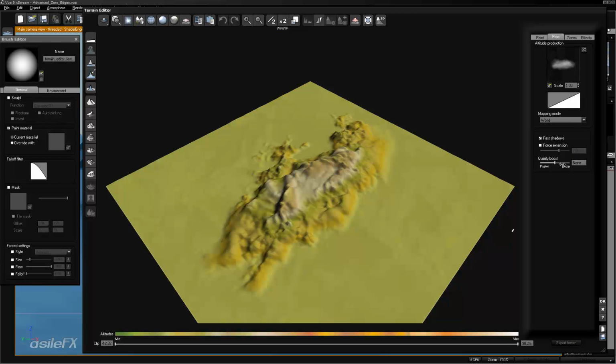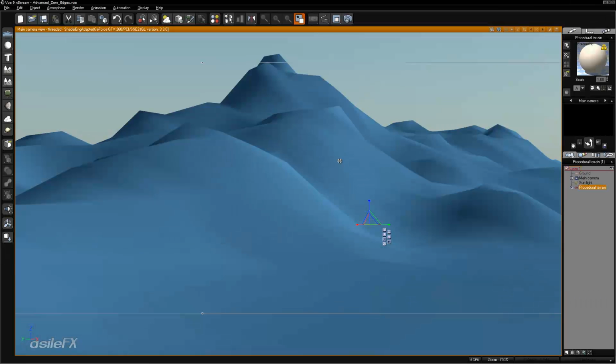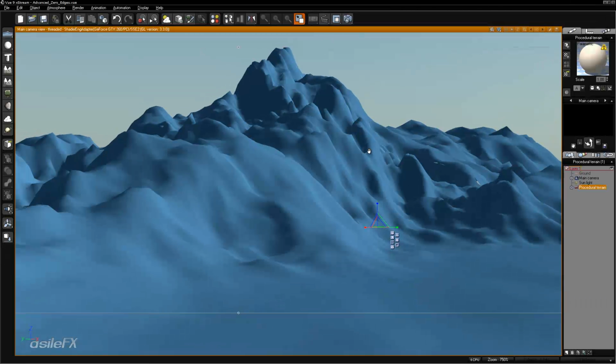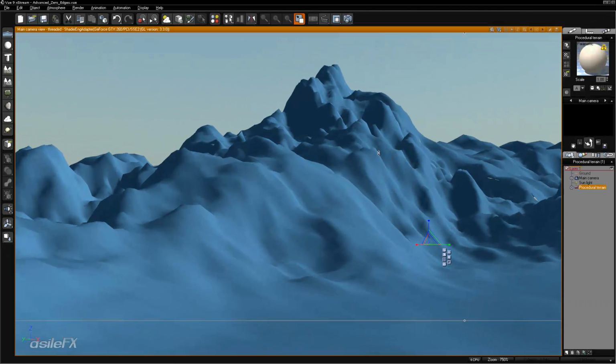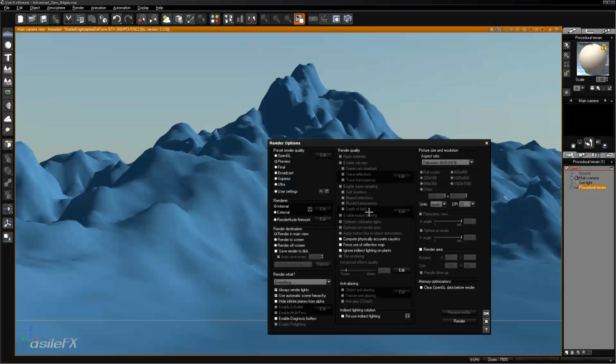It does appear as if maybe they've reduced the quality boost within View 9 since View 8 to get a faster render, but that might be because of that removal of the z-axis. So really not quite sure. If needed, increase the quality boost, because I have noticed a little more tearing in View 9 than in View 8, but not that bad, just in a couple of different nodes in certain circumstances.